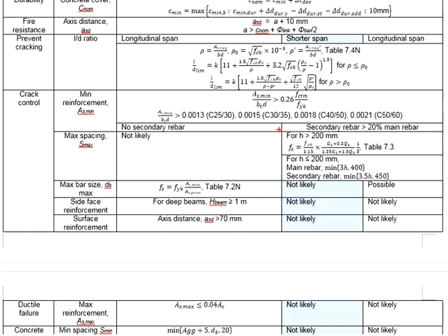As for the slab and the staircase, normally you will need to check for the maximum spacing, as the cross-sectional area of the slab and the staircase are normally relatively large as compared to the loads acting onto the members. The requirement for the maximum spacing varies depending on the thickness of that particular member.